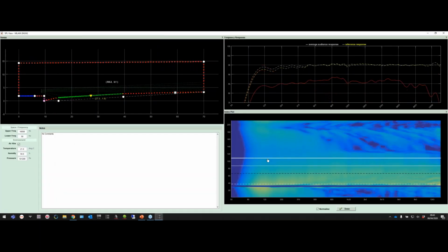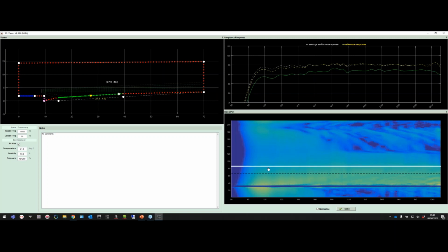So just by dragging through, we can see there that even though we have a lot of boxes overshooting there, it's doing well to keep the SPL down low and increasing up. So even there, we have no boxes firing at that, but the response is pretty consistent. So it shows you the power of these systems. And of course, in the near fields where we've got a big gap between two optimized boxes, and then diving straight into a non-audience is where we start to see a bit of filtering from the system.